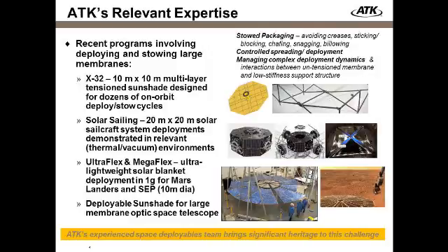Well, we did one of the initial solar sail deployments, and that's a picture of the top view at Plum Brook. So this was 20 meter by 20 meter, about 100 feet across if you look at the diagonal, and deployed that in vacuum and at both the temperature extremes, and showed how that would operate there. We are developing Megaflex. Here's a picture of our EDU wing that's basically going to Plum Brook next month. We'll be deploying that in vacuum, and that is 10 meters in diameter. We'll produce about 20 kilowatts per wing, and extensible up to a 30 meter diameter, which would create power of about 175 kilowatts.